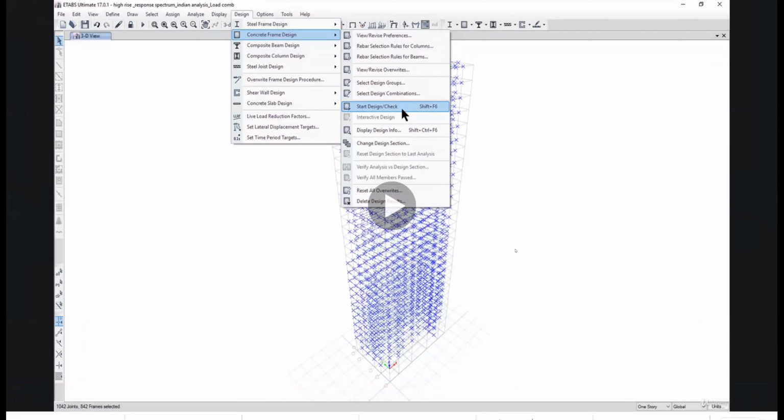So for the column design, one set of combinations is there, and for beam design, one set of combinations is there. Since it is a high-rise building and a complicated structure, you have so many load combinations. But for low-rise buildings like G+5 and apartments or any industrial building, if there are no earthquake forces, then we can directly take for the design 1.5 times dead load plus live load. That is more than enough.